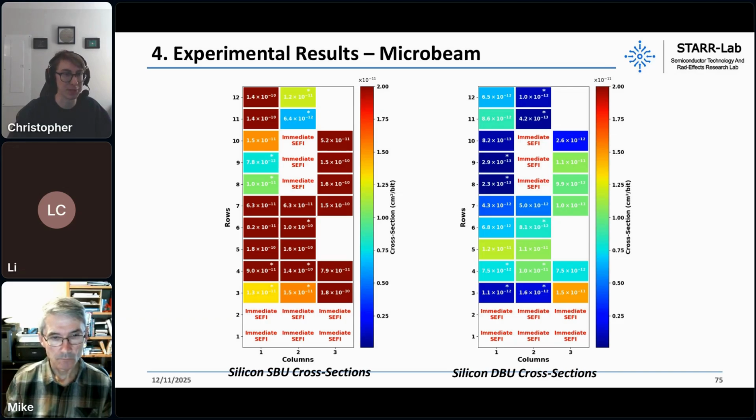So we couldn't reliably get all the single bit upset and double bit upset information off the memories before the device would crash. But that was quite interesting, because obviously some of these blocks are quite sensitive to inducing a software failure compared to others. It's neat that perhaps those blocks must be storing a lot more information related to the general program flow or really critical operating system information, something that would cause the device to crash.